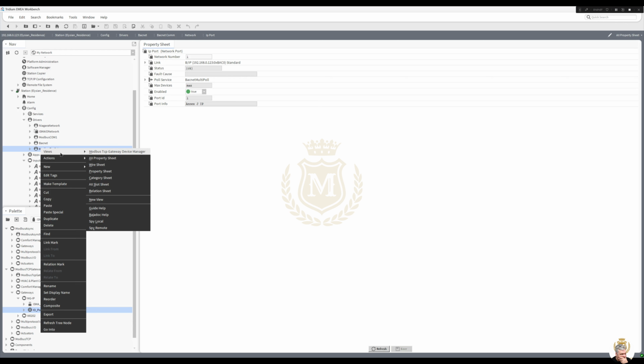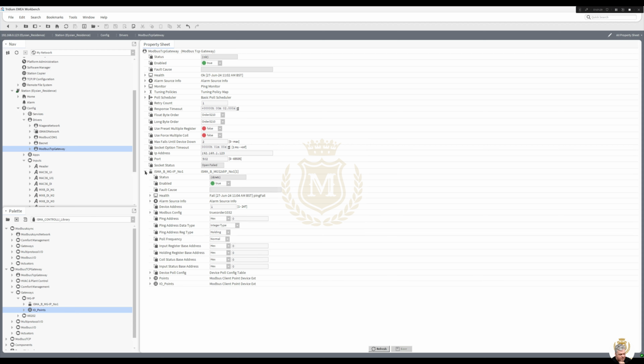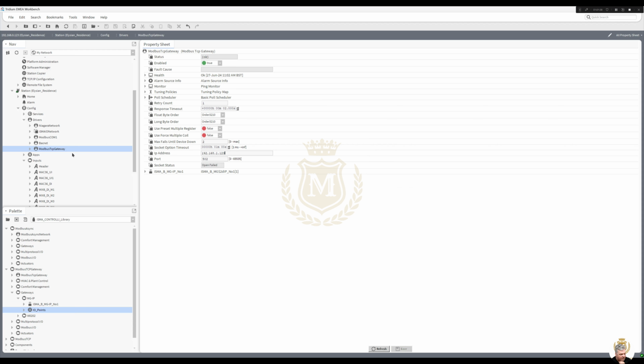And then that one, views AX. The IP address of the Modbus gateway, I think it's going to be 192.168.1.123, which is the same IP address at the moment of the controller, except I'm using 0123 at the moment. Yes, you will be down. Okay, we can leave that as it is, because nothing's going to happen there until we're on site. 502 port, which is a Modbus port, which is right.